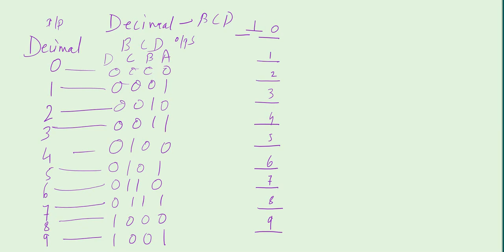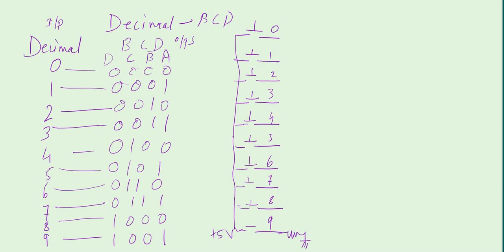They can be in the form of a push button key. So this is the 0 number key. Exactly similar keys are here for every input. Whenever the user presses the corresponding number, the user has to press the key and only then will the input be connected. Otherwise it is considered to be connected to 0. So this is a key, and all these keys on this side will be connected to plus 5 volts. Whenever the key is pressed, the line will become high. It is expected that each key is otherwise connected through a resistance to ground. It may not be shown, but it is connected this way.